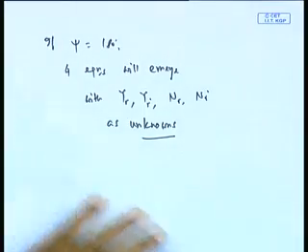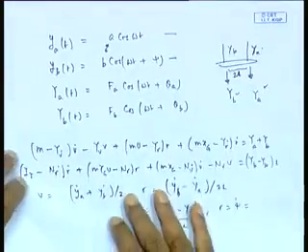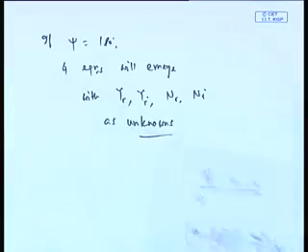So what is happening? Why I wanted to show you this tells me an interesting way. Supposing I don't keep psi equal to 0, you don't make it pure sway, you don't make it pure heave. I can make psi equal to 45 degrees, I get 4 equations with 8 unknowns. I take psi equal to another angle, say 90, say 135 degrees or whatever, I get another 4 equations with 8 unknowns. So I will get a total of 8 equations with 8 unknowns, I can solve for it. Therefore PMM as a technique can be generalized. You need not necessarily give psi equal to 0 and 180, or pure sway, pure yaw, although that is what is done. I can also have sway yaw mixed, make 2 experiments and separate it out.